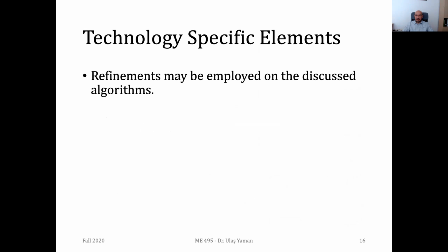So now let's focus on some different issues about the software in additive manufacturing. Depending on the technology you are using, whether it's fused filament fabrication, stereolithography, or powder bed systems, we may have some variations in terms of slicing. For instance, in powder beds or in SLA, the interior should be completely filled. You should completely be curing the internal material. But in fused filament fabrication, as you know, we may have just 20% infill or just 10%, but this is not valid for the other technologies.